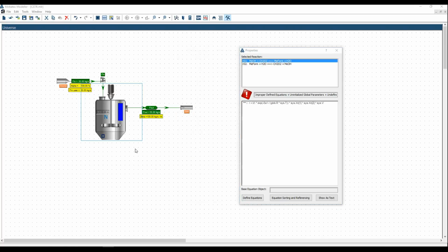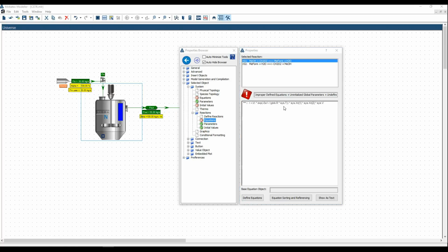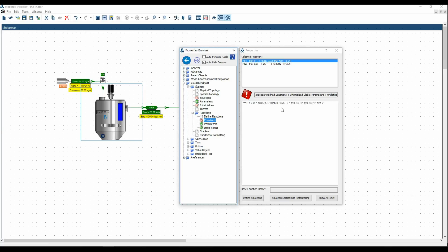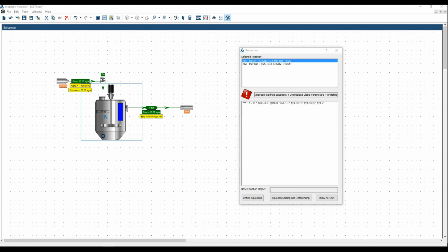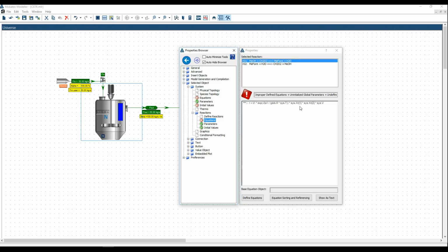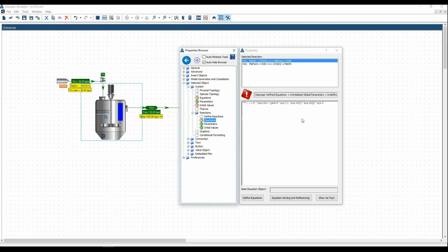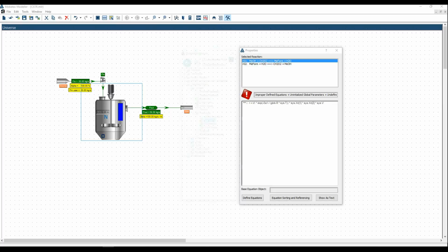Sys dot prefix is used in reaction equations to call the variables from the system where the reaction is added. So in this equation we are calling the system temperature and volume, as well as molar fractions of species 1 and species 2. These are explicitly written vector variables, which now become scalar variables, and the numbers 1 and 2 are reference to a specific species.